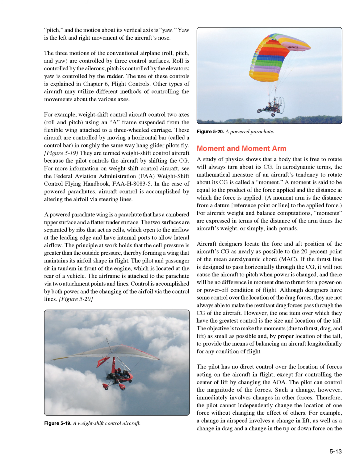Although designers have some control over the location of the drag forces, they are not always able to make the resultant drag forces pass through the CG of the aircraft. However, the one item over which they have the greatest control is the size and location of the tail. The objective is to make the moments, due to thrust, drag, and lift, as small as possible and, by proper location of the tail, to provide the means of balancing an aircraft longitudinally for any condition of flight.